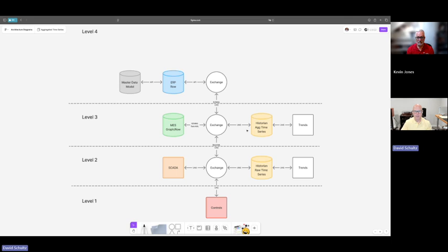So the idea is that people sitting at that business level, level 4, may want to be able to see some trend screens. Well, the trend screens that are going to exist in this aggregated time series are, more often than not, going to have the fidelity and the resolution of the data that they need. And it's a less expensive way to both ingest and store that information. Again, the historian is going to be specialized and column-based, and we're going to utilize unified namespace type models to exchange this information.